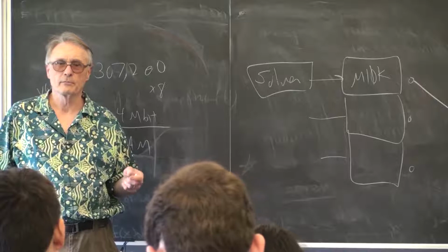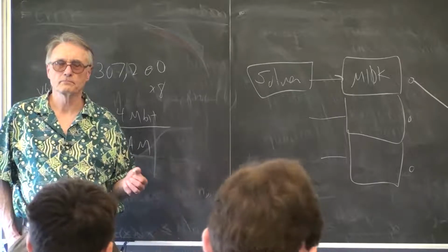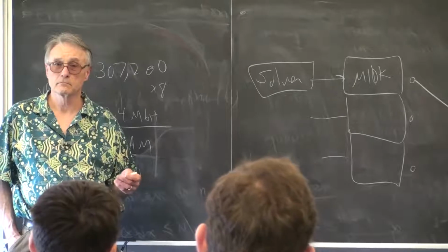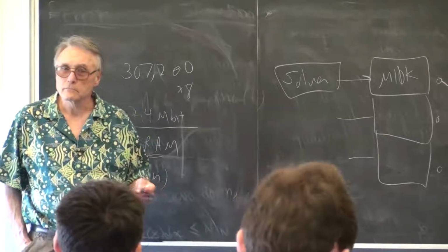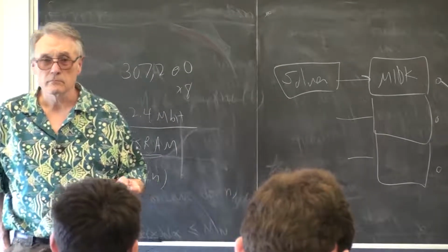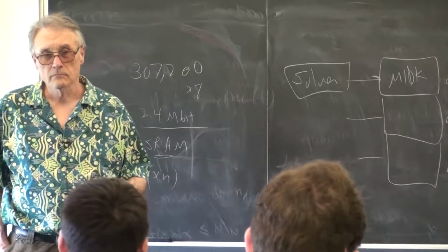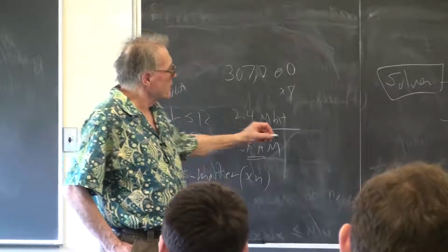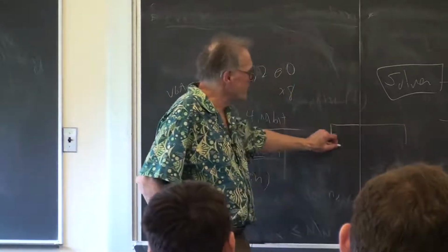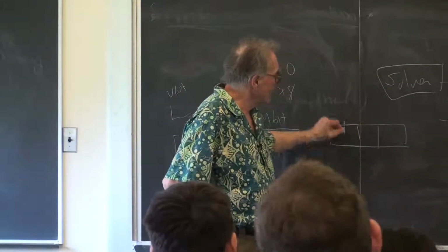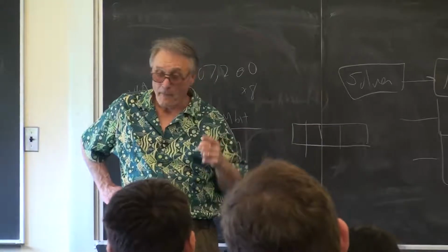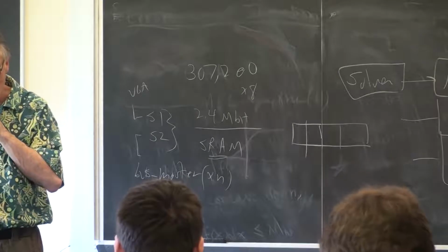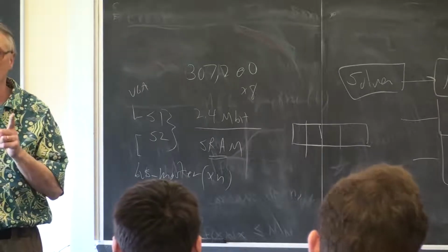What else on Lab 4? Are you able to do wider writes to the VGA memory? So set up your solvers to actually compute 4 pixels at a time. Oh, what an interesting idea. So could you, since after all the bus is a 32-bit bus, could you do 4 bytes at a time? I think so.